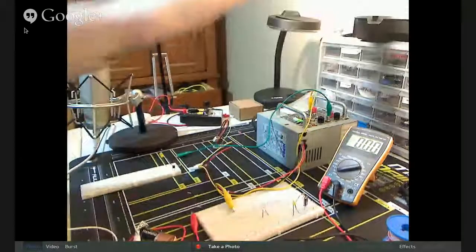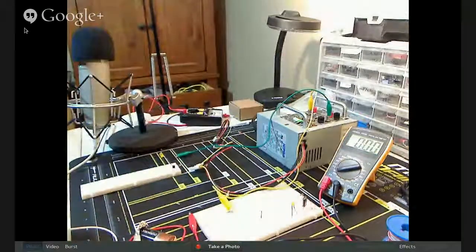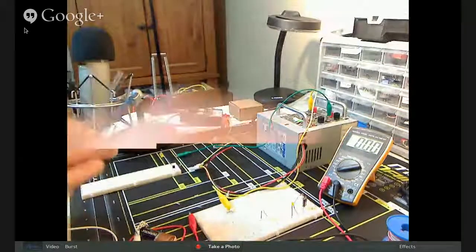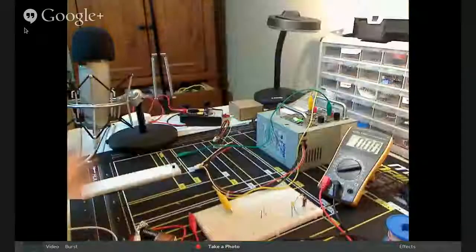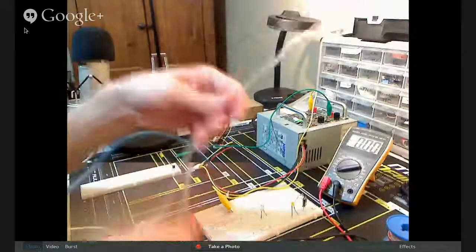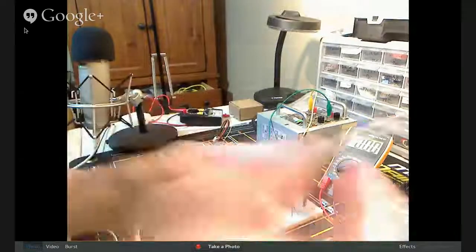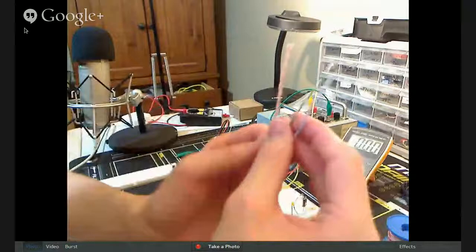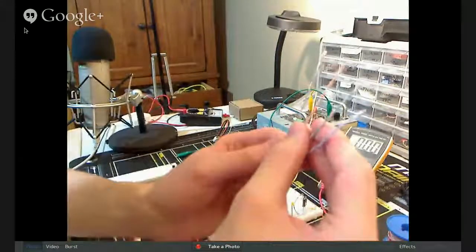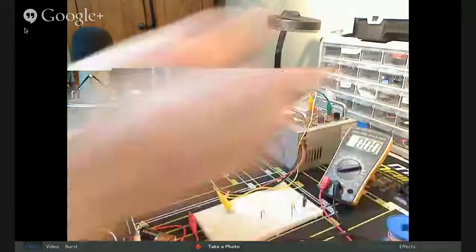Just pull it, and that'll cut the rest of the outer shield. It's nylon or something. And we'll be able to pull the twisted pairs inside and discard the shield. There'll be 4 wires inside, and we just need one of them. It doesn't matter which, but I think the brown one. The brown one's the least twisted.